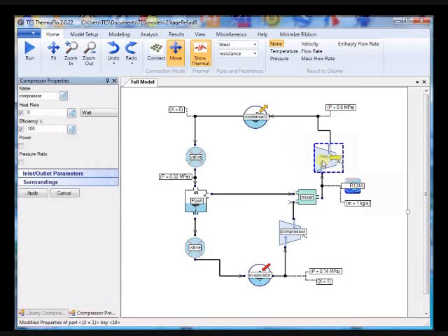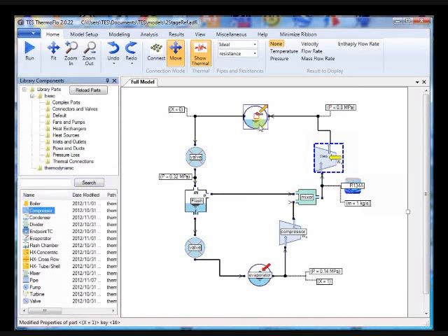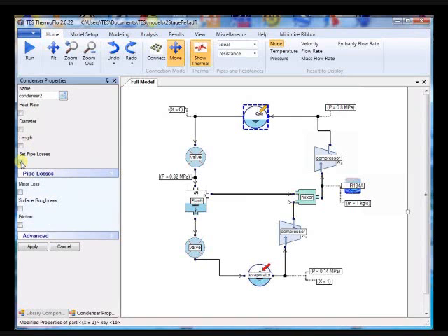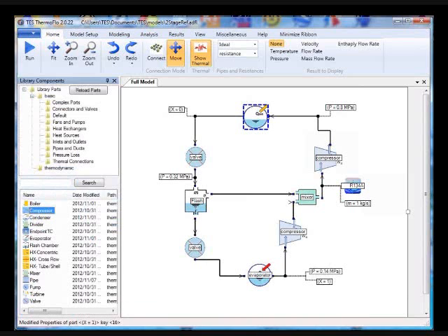Now let's look at, if you wanted to see the compressor, you double-click on it. It takes you to the menus. Whatever's not checked will be calculated. So, and then you go on. Let's look at the evaporator, for example. You can look at the things if you wanted to use. Here we chose to give the pressure drop of 0. That's the ideal thing.